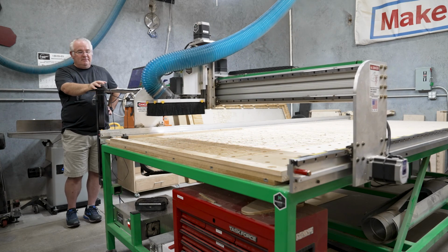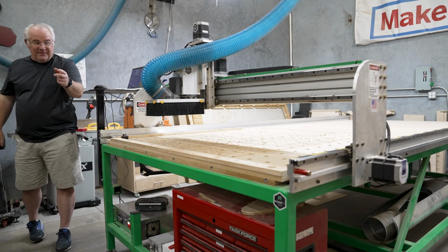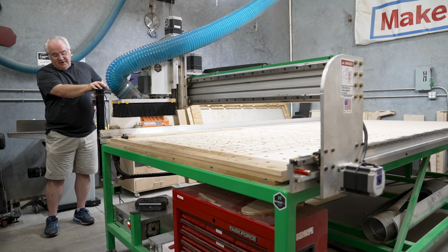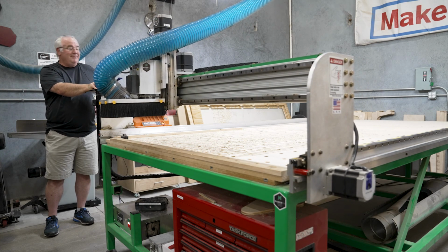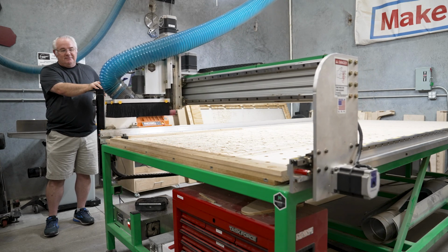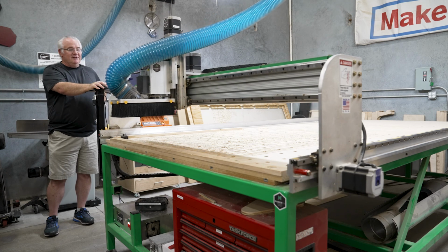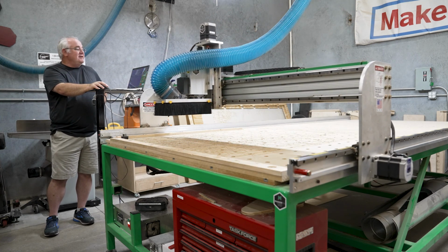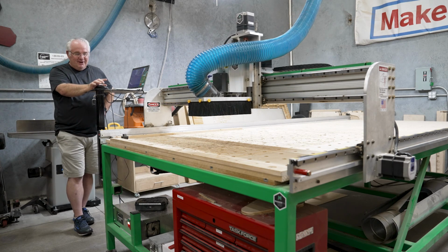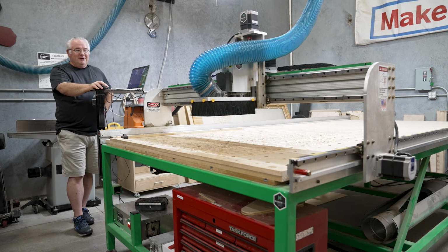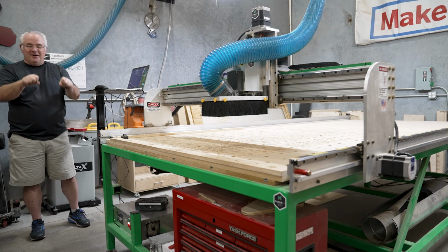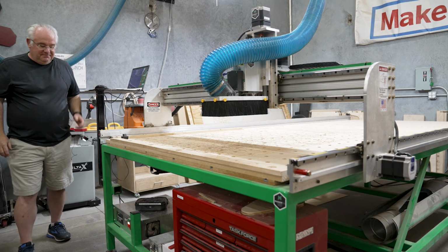At this end, there are physical end stops, one here and one there. So you will not be able to run this thing off of it, but I want you to hear what happens. Okay. So we're going to reset home position, but if for some reason you hear that you've hit the physical end stops, please try to avoid doing that intentionally. You probably lose the home out there, right? We've now lost the home position by what I just did, yes. But we're likely going to lose the home position anyway as you learn to put that nut on. Some people can be really strong and will cause the gantry to move.